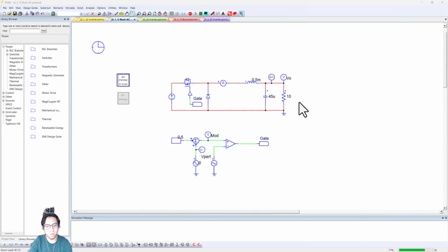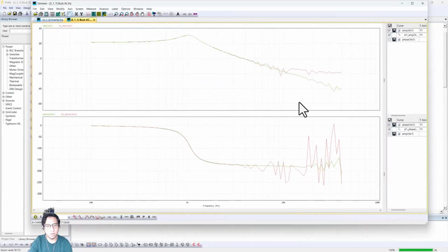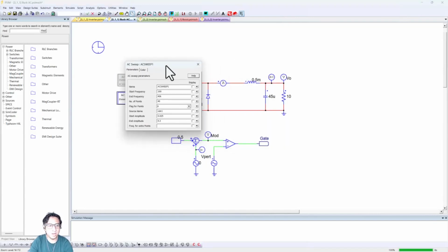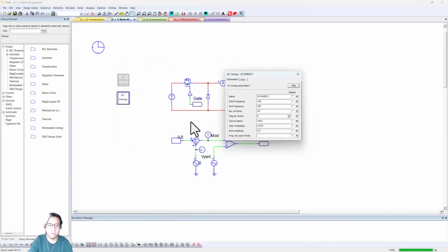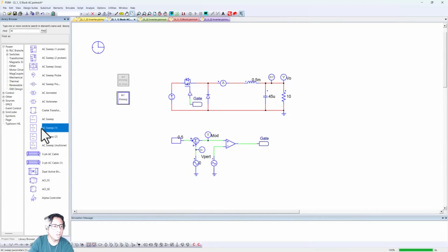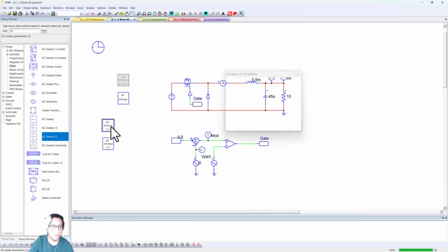Just going to wait a bit more. There it is, and it actually did by a lot, right? So in this case, maybe we need to start thinking about the original or the first AC sweep, because with this, we can actually define an end amplitude. At the low frequency range, we'll start with one amplitude, and then at the end, we'll start injecting more signal. And the same thing goes for the other AC sweeps; something similar goes with the other two.